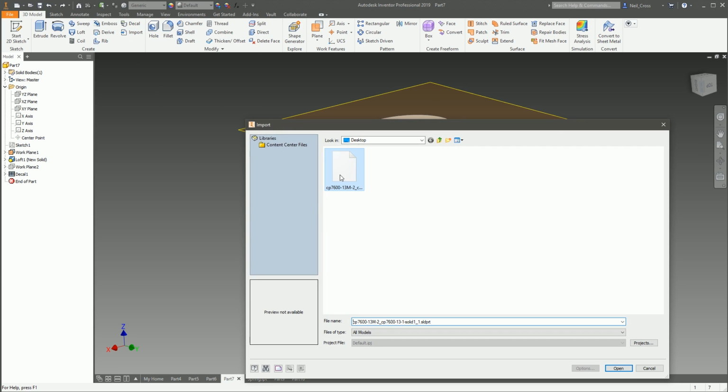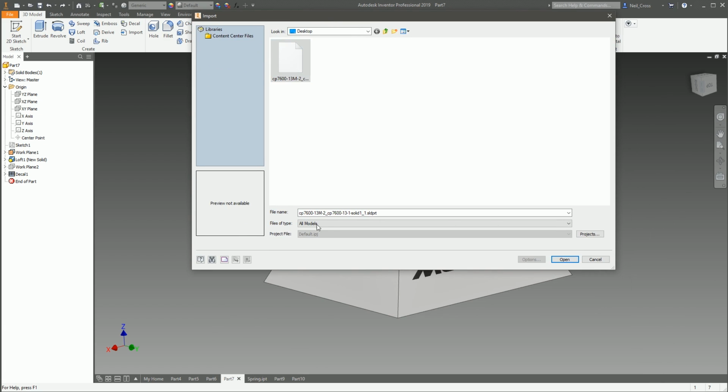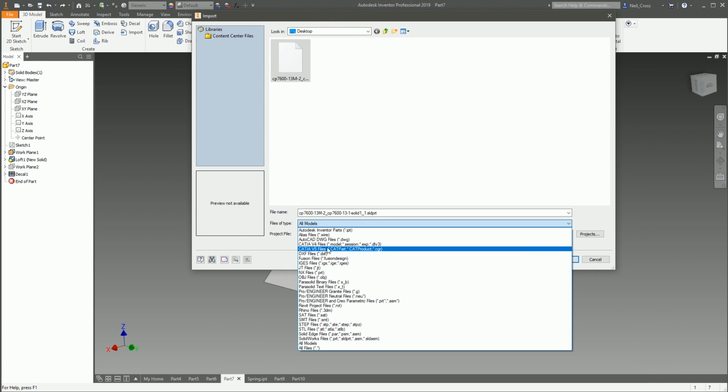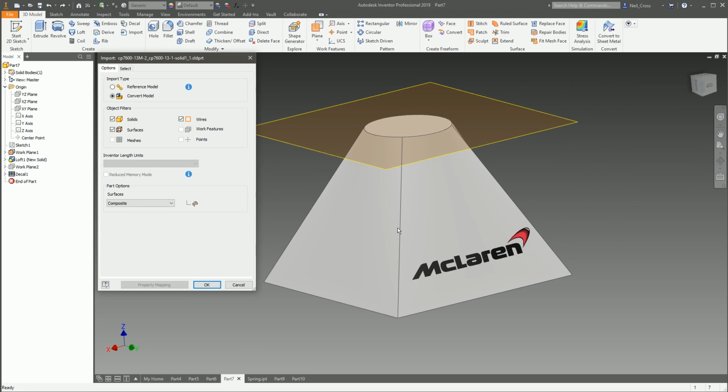So we can select import. This thing here is a SolidWorks part, SLDPRT, but it will search for files of, wow, that's gone off the screen, hasn't it? But it'll search for files of CATIA nature, of Pro Engineer, step files, SolidWorks, Solid Edge, loads of different file types. But then you browse to that file, bring it in, and then Inventor activates its AnyCAD system, which is something that's relatively new to Inventor.